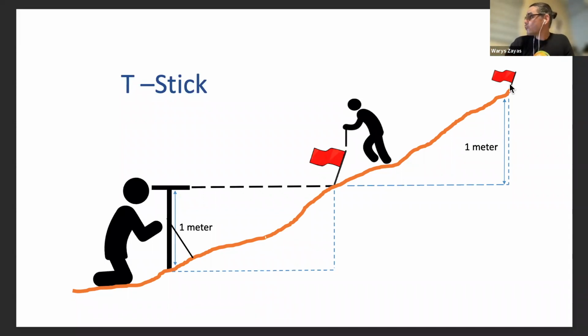Then you start to walk down the slope, and at some intervals you just stop and place your stick and look to the sight. When you identify the bottom point of reference, the bubble levels are at level 0 when the bubble is in the middle, right? That's what indicates that it is level 0.